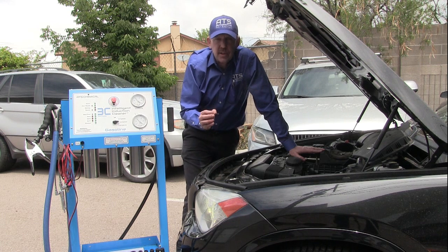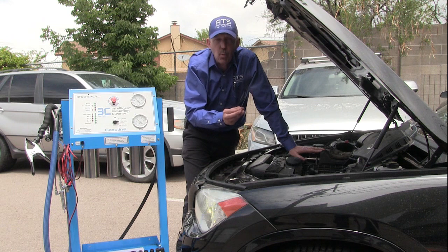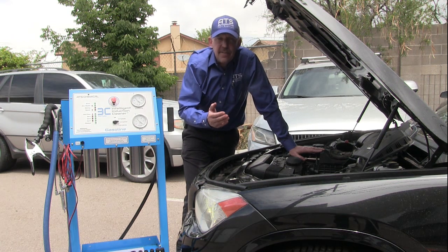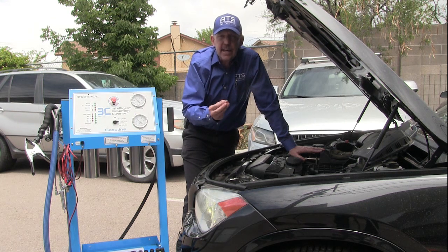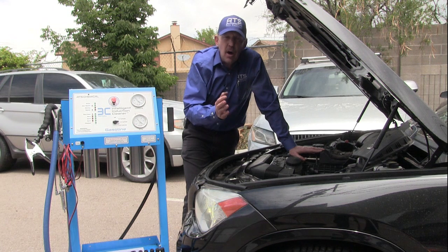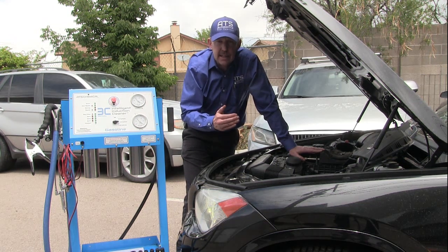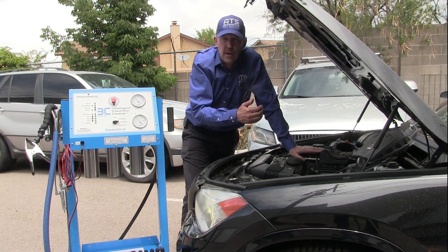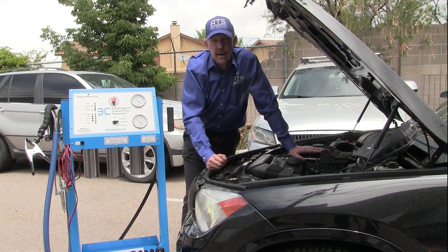We would never put the chemical on maybe a brake booster line that's on one side of the manifold. Many times the brake booster lines, that's more a packaging concern. It's easier to catch the vacuum on one side of the manifold. Now if we put the chemical into the intake and it's all on one side, we'll put all the chemical into one or two cylinders, and if you don't damage the motor, you're going to damage the cat. So we don't want to do either of those.